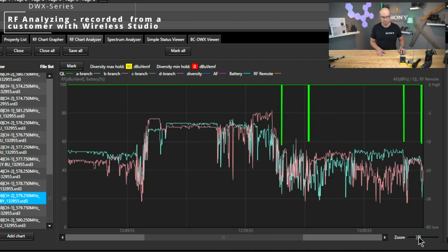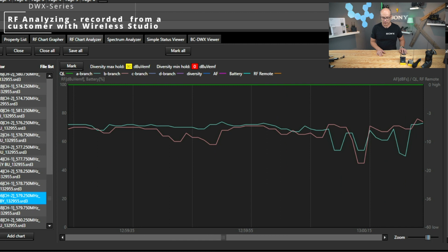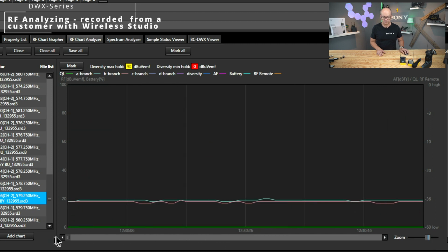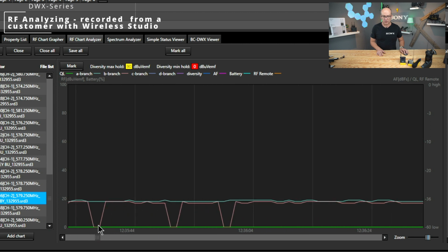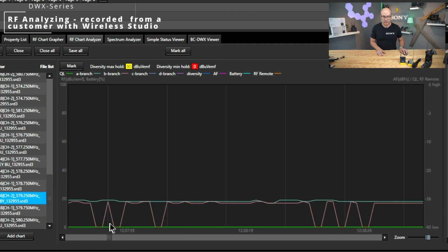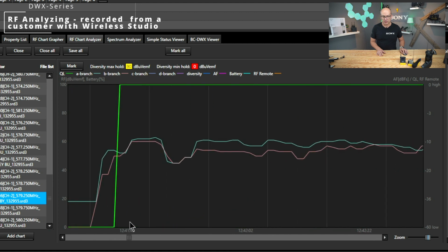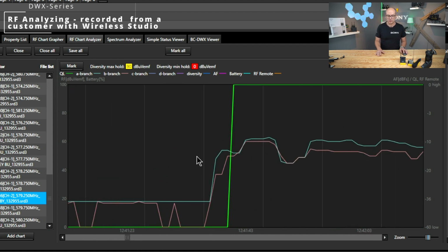Let's zoom in on channel number 36 and go over. What you see here is that your noise level is around 20 dB. So if your noise level is around 20 dB, then your signal noise ratio with plus 25 means that it has to be minimum 45 dB, which is fine here. It's between 60 and 50, so that's okay, and that's why it is working. But you have to take care of what your noise level is. If the noise level is too high, switch to another channel.